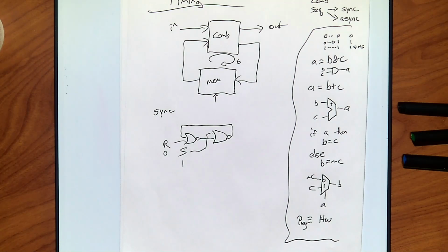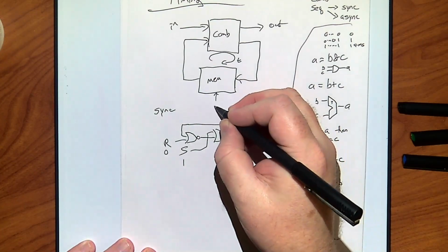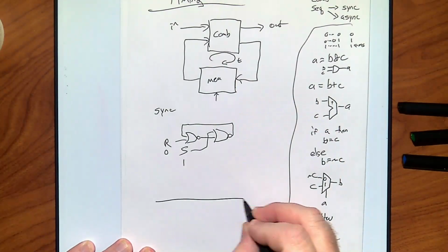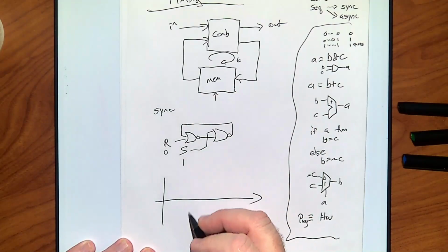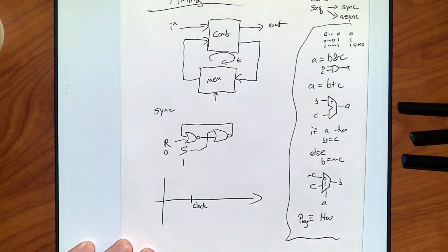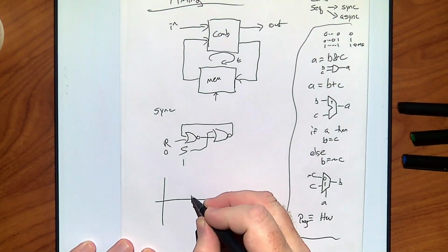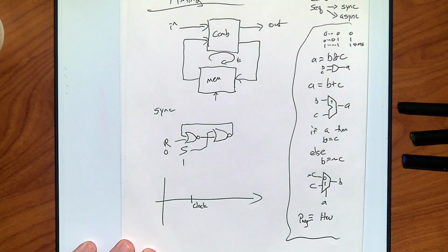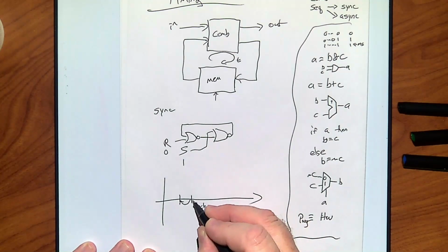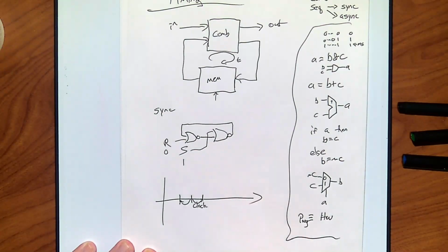So we would want to protect these. Well, we make a requirement. Imagine this is when the clock hits. Again, we're doing a timing. So let's say the event hits partway. Maybe I'll just draw it as a timeline and then I'll show you here. Let's say the clock hits right here. This is my clock's positive edge. At this period, I want my inputs, set and reset or whatever else, I want them to be stable for a little time period before, and I want them to be stable for a little time period after. Make sense? This is my safety margin.